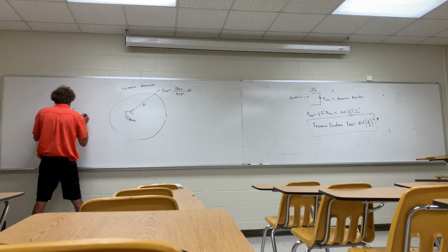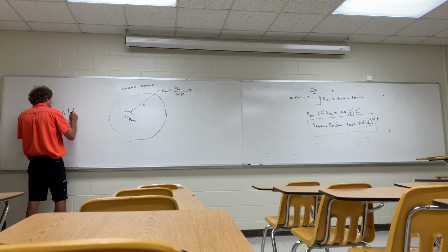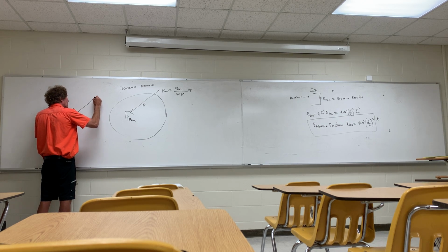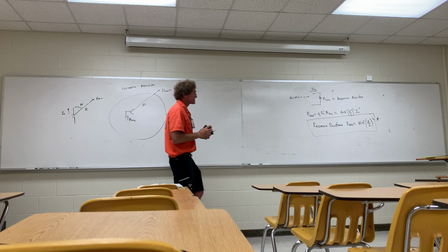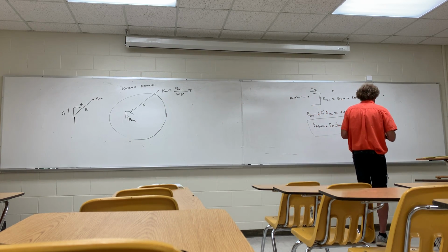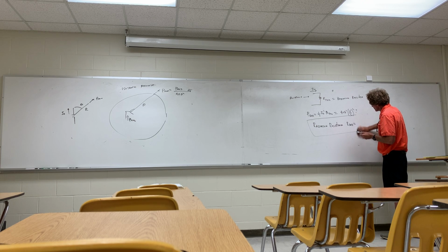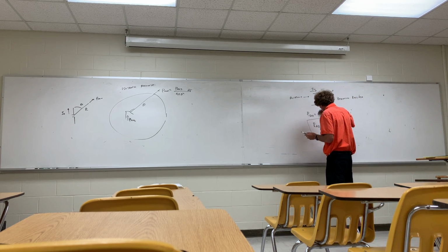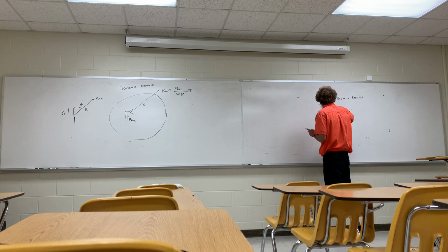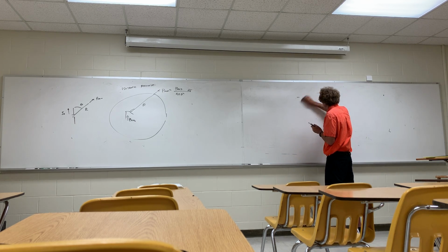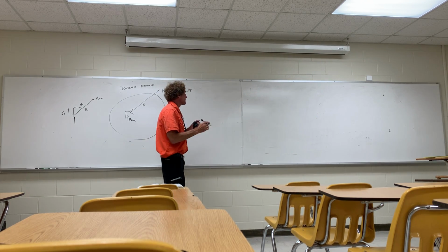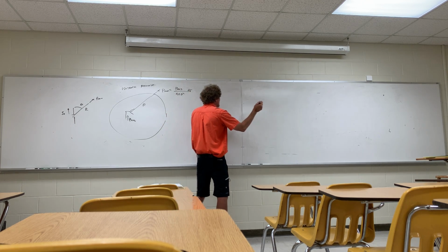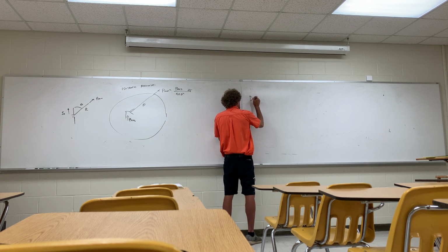So now I got my short dipole, got a current I naught, and I know what Pav is, the average power density, as a function of angle and R. So to go about getting this is probably the easiest way to see it. We talk about the directivity D,